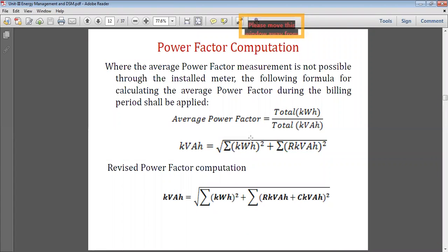No doubt, if you are increasing the large number of small capacitors, you can give fine adjustment in the power factor, but there is a limitation. So for that, we have divided the capacitor into 3 kVAr and 2 kVAr, so it becomes 5 kVAr. If you need 12 kVAr, it starts one 10 kVAr unit and one 2 kVAr unit. If you are keeping only 5 kVAr and 5 kVAr capacitors, then you cannot find the value of 13 and 12 kVAr.